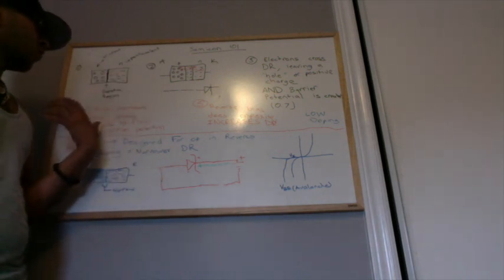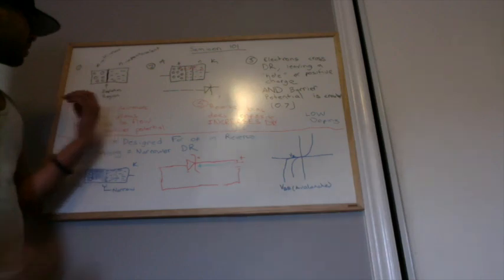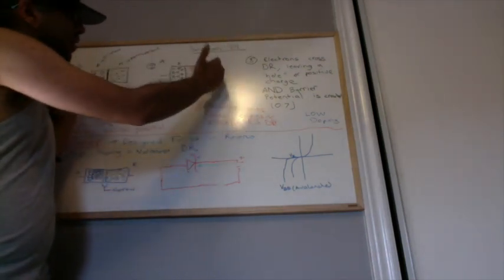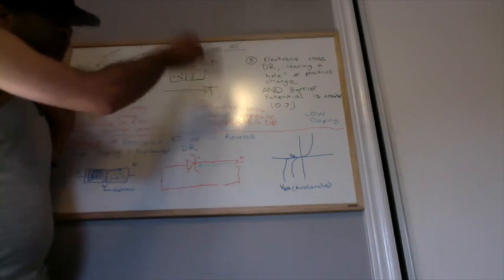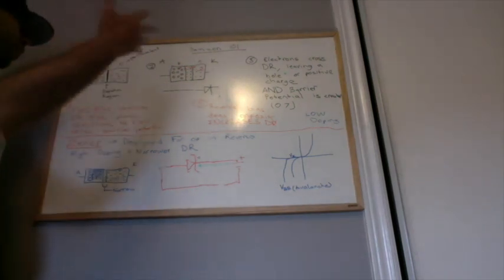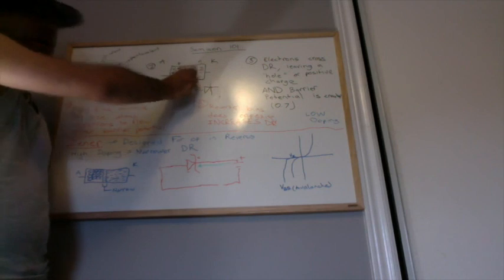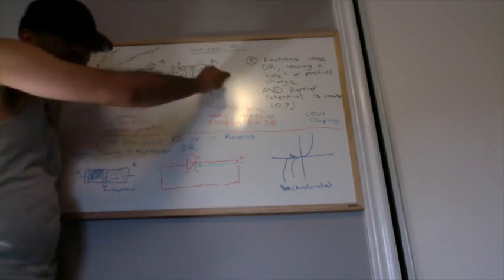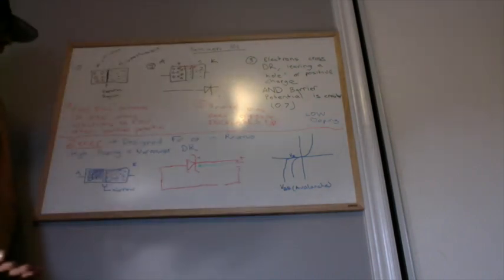Now, what happens in this case is, as we are moving the holes and the electrons as a result, the forward bias decreases this depletion region size, and all of a sudden holes are able to jump, positive charge carriers are able to jump, and we have current flowing through the diode.